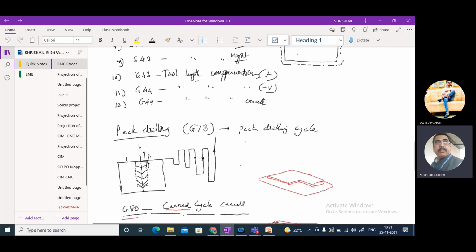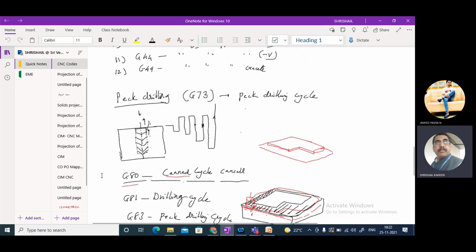If it is a small hole, initially we are going to create this hole. Continuously, we can drill it very small. And how will the scrap come out in the drilling operation? How will the scrap come out? It will be coming in the form of a continuous chip or simply in the form of a discontinuous chip. That is one. And where is the provision for the movement of the scrap from the depth? In the flute, there will be a spiral structure. In that gap, this will be moving.